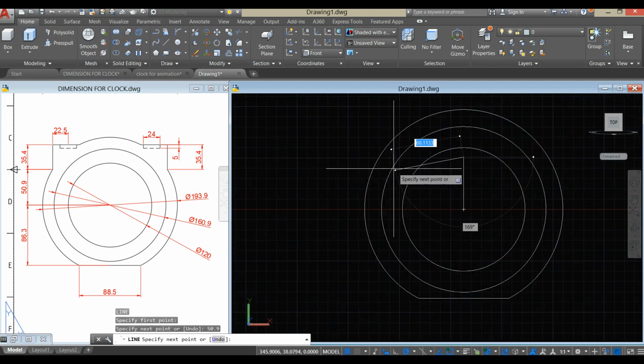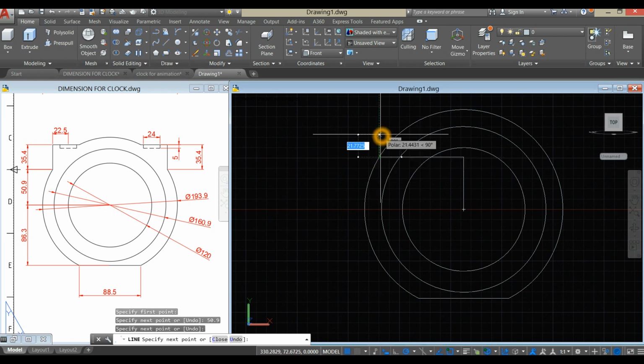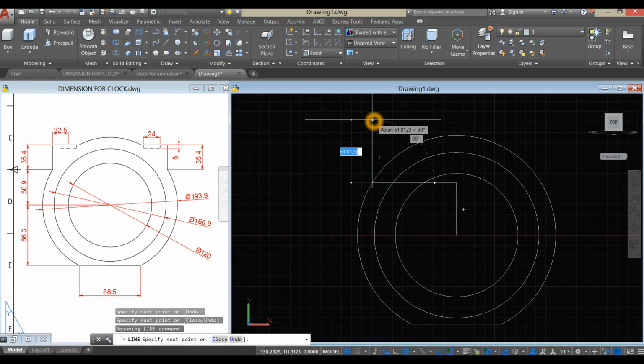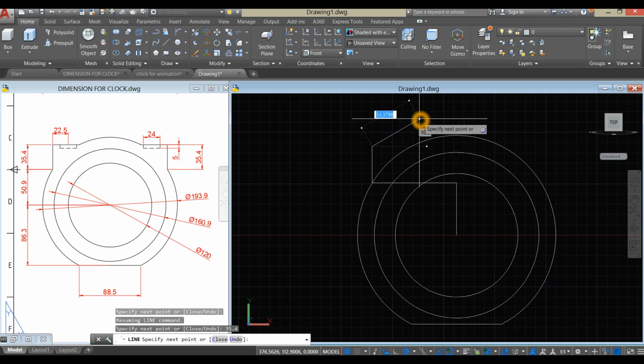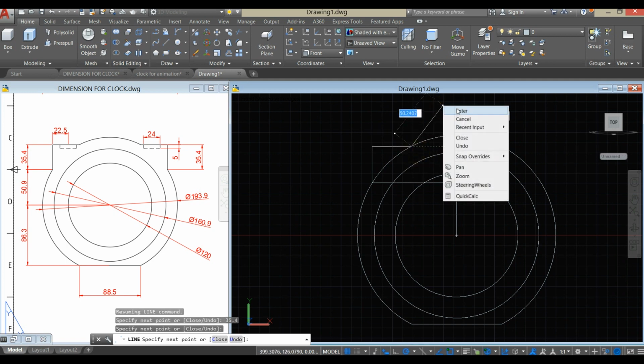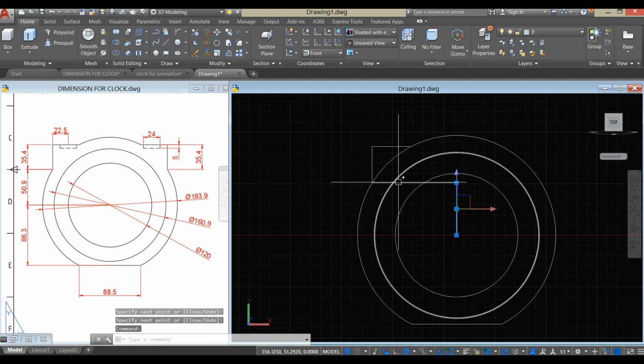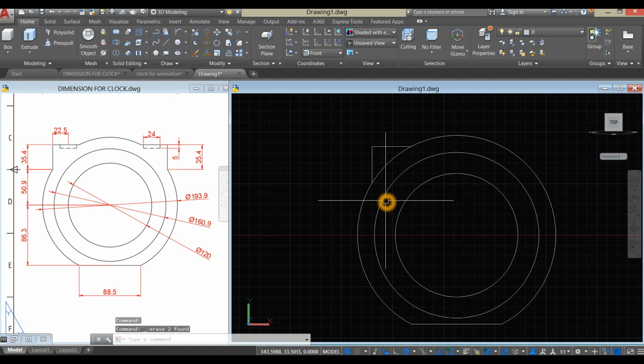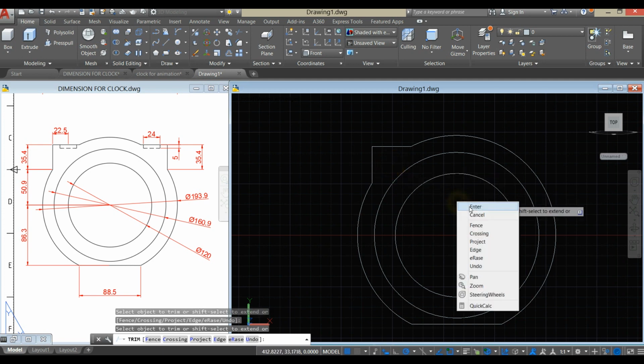Bring your drawing to the left and click that intersection. Bring up your drawing for 35.4. Bring it to the right and hit that intersection. Now I'm gonna remove this one, delete that, type TR for trim command, enter twice, and remove this one.